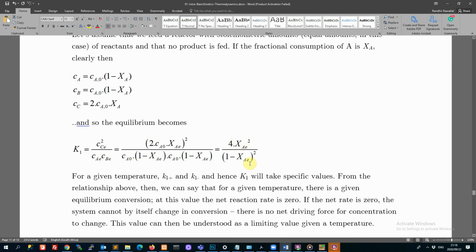So the equilibrium conversion. We'll be able to say, if I apply a temperature of, say, 500 Kelvin, I can then tell you what the equilibrium conversion will be. Maybe it's 40%. So I know the tendency of the system is towards 40% conversion. And that is telling me how nature is going to behave. It's telling me if I'm applying 500 Kelvin, nature is going to want to go towards a level of 40% conversion. And so then I can design my reactor around that.